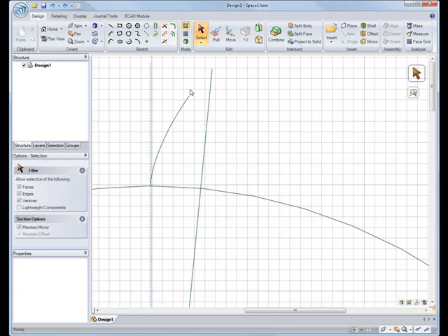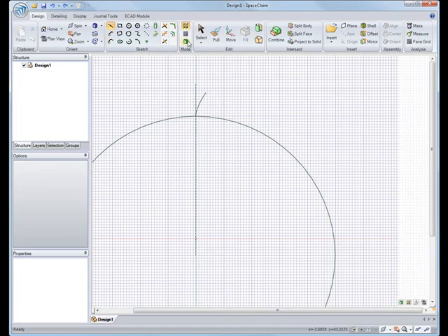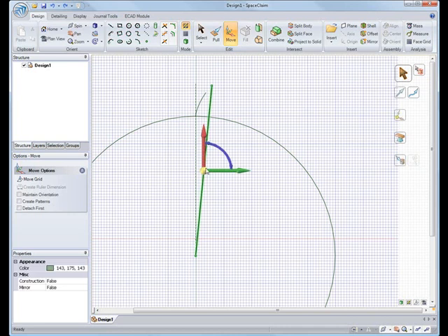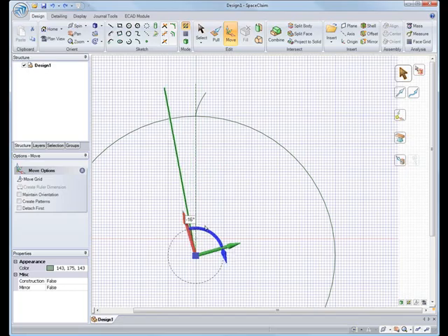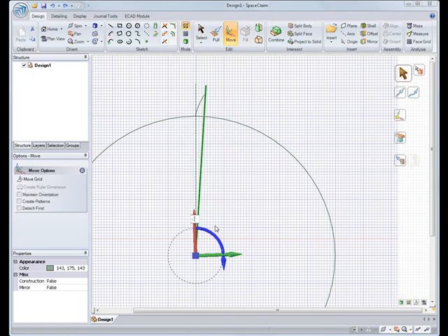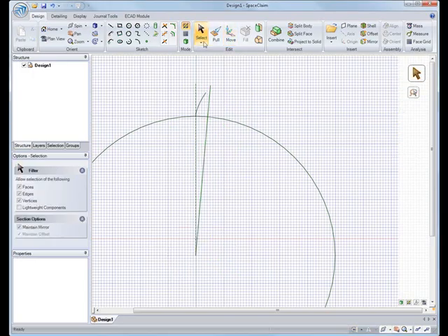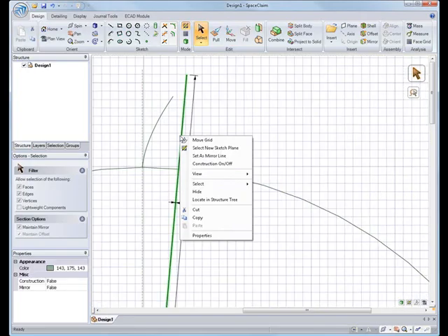So let's go back and change this line that I made. Let me redo once to bring that back. And I'll change the angle just slightly. We'll change that by, let's say, a half degree. So we'll pull that in by -0.5. This way we'll have a little bit more space between each tooth. And you can control this by whatever the gap needs to be.